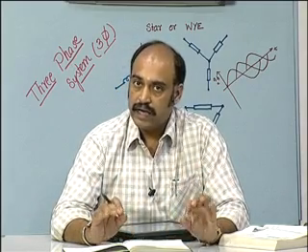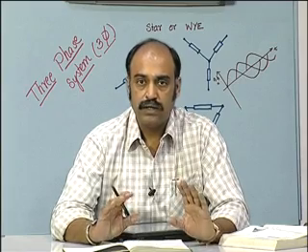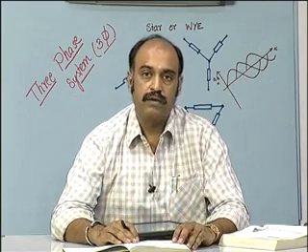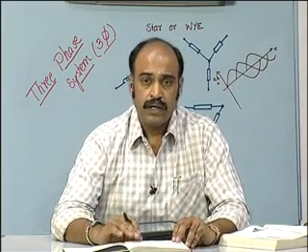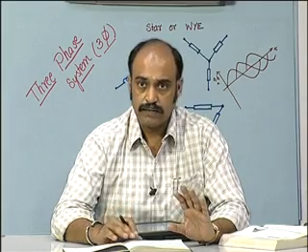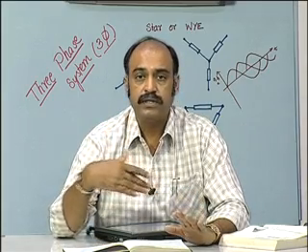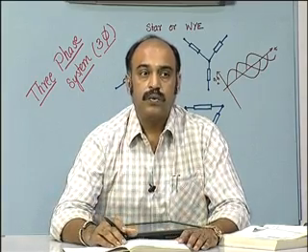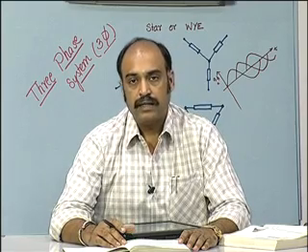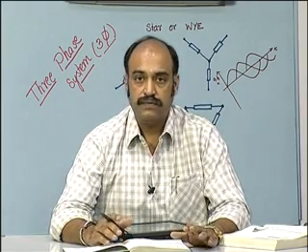That would give you the equivalent total power that is drawn by the 3-phase load. If it is a 3-phase 4-wire system, then just connect 3 watt meters, add up the 3 values, and you get the power. We stop here and then continue the next class with 3-phase transformers.